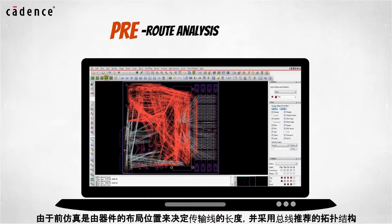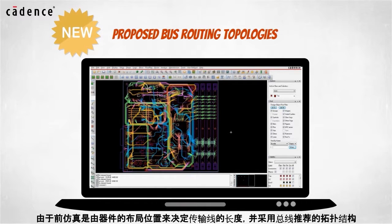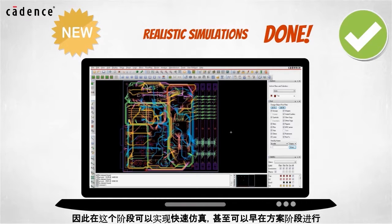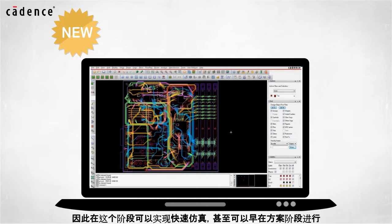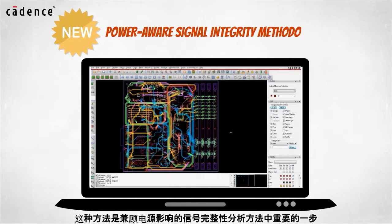Since the pre-route analysis uses transmission line lengths based on the Allegro component placement and the proposed bus routing topologies, realistic simulations can be run very quickly at this stage before routing of the PCB even gets started. This approach is an important step in a power-aware signal integrity methodology.